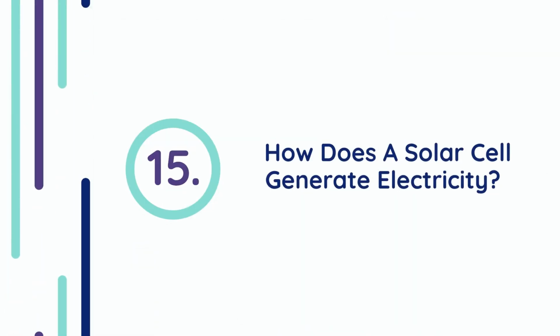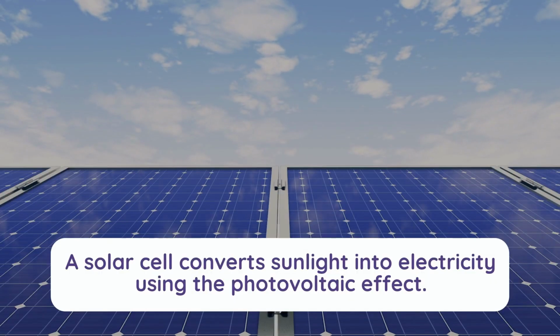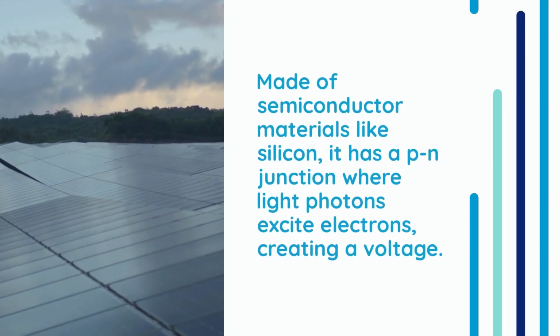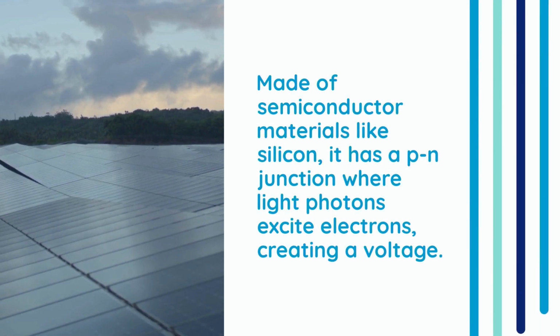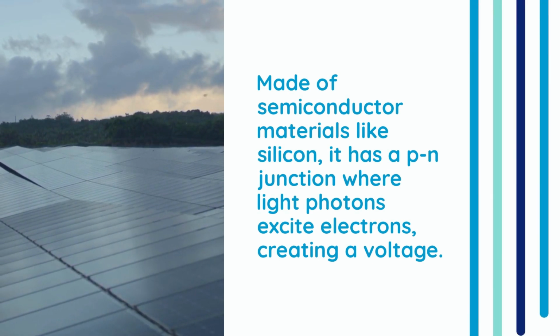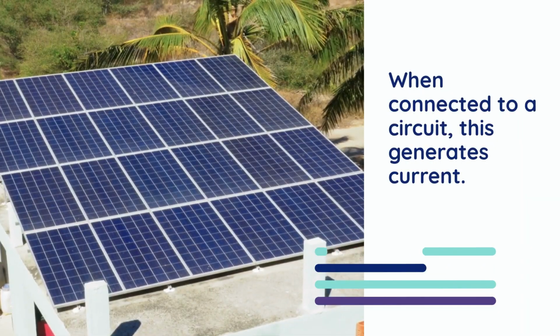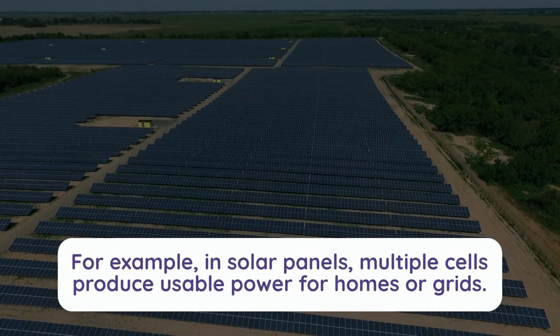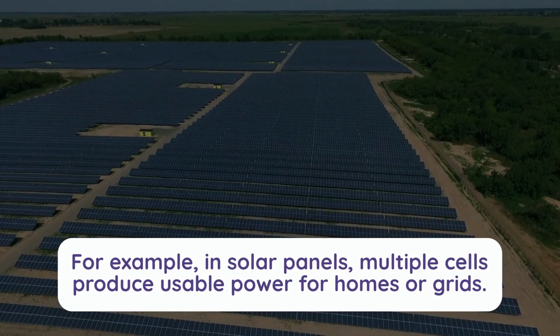15. How does a solar cell generate electricity? A solar cell converts sunlight into electricity using the photovoltaic effect. Made of semiconductor materials like silicon, it has a p-n junction where light photons excite electrons, creating a voltage. When connected to a circuit, this generates current. For example, in solar panels, multiple cells produce usable power for homes or grids.